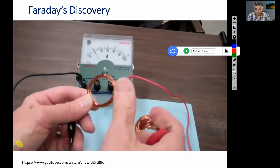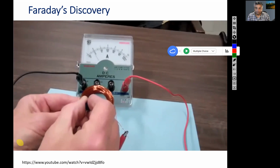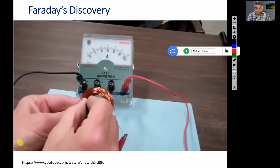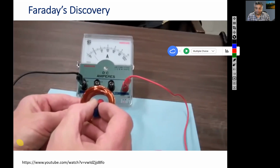And now let me connect the 100 loop coil. N is now 100. Maybe it was 10 before. Moving the magnet in very slowly, you see a deflection to the right, pull it out, to the left. If I go in quickly, you see a much greater deflection. So the rate of change of the magnetic field affects the current also.